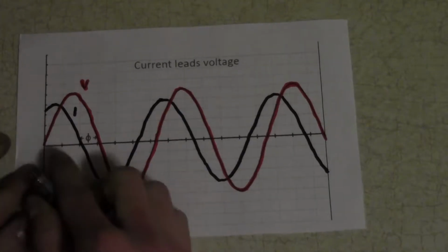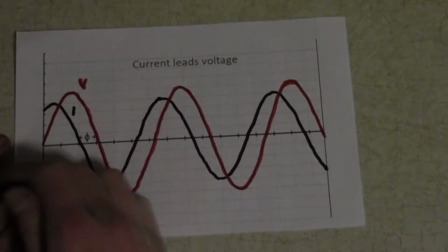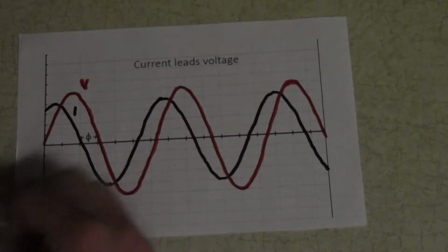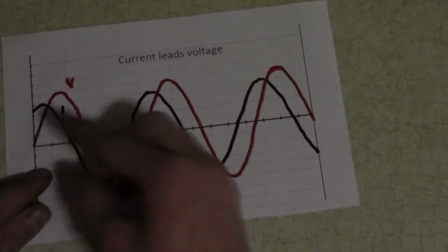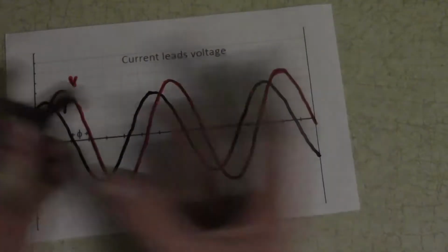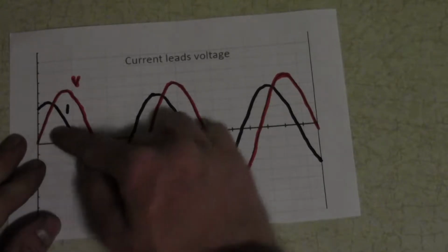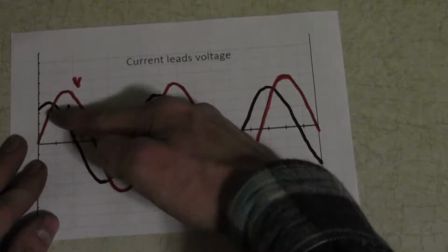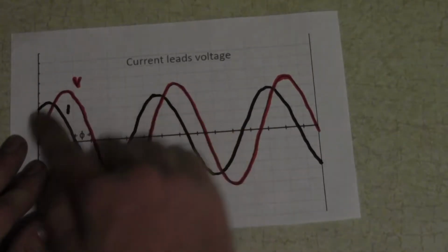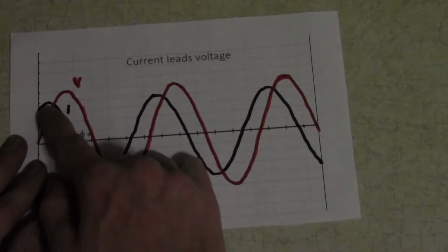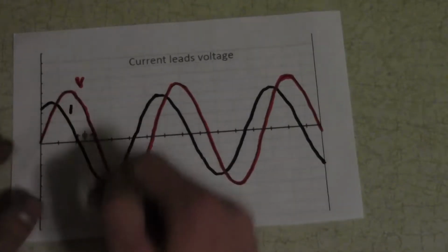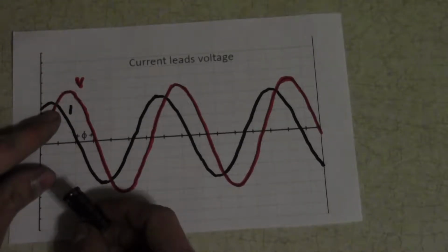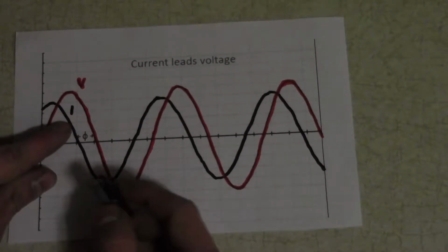What happens is, when you're at 0 volts and you start off from the beginning, this capacitor is fully discharged. So as the voltage increases from 0, this capacitor is drawing a huge amount of current, and it takes a lot of current to charge this capacitor up, even to these lower voltages. Before this voltage gets to its peak, the current going to the capacitor is beginning to taper and drop off. The capacitor is approaching the fully charged state, and so it no longer requires this massive amount of current. So the current begins to decrease.